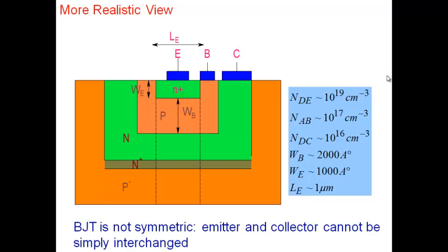Now you can note that the two transistors are isolated from each other. How? How is the collector of this transistor isolated from the collector of the other transistor? Well, how do you go from one transistor to the next transistor? You'll have to go through N plus, P minus, and then the other transistor would also have an N. If you start from one transistor, whose N is here, then you'll have to go to the substrate, and then go to the next transistor, whose N region is there.